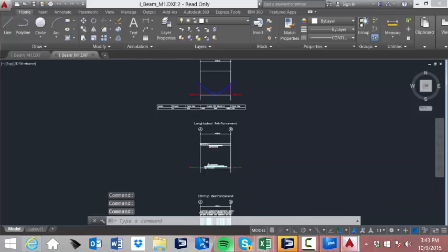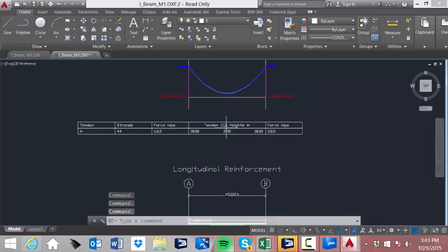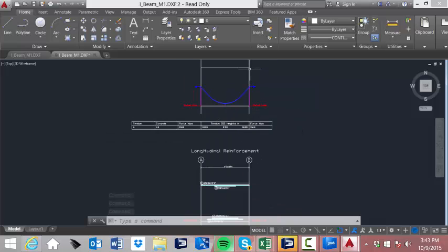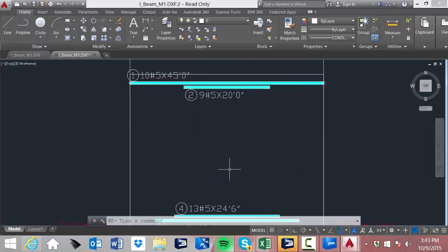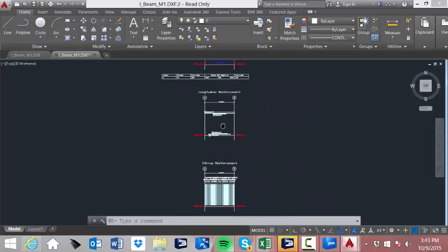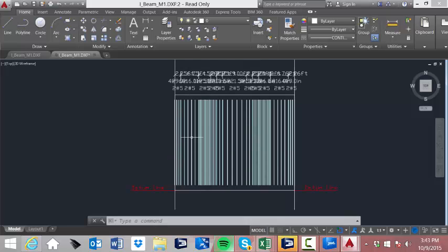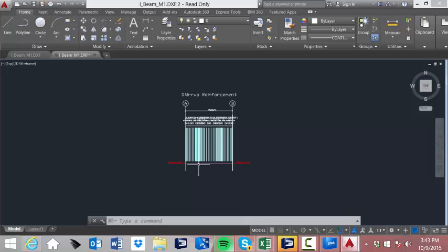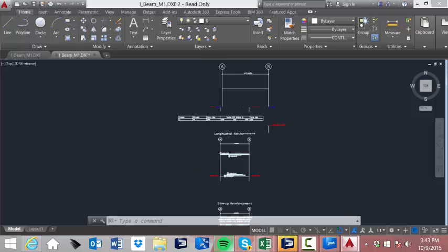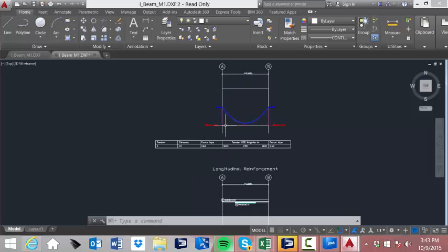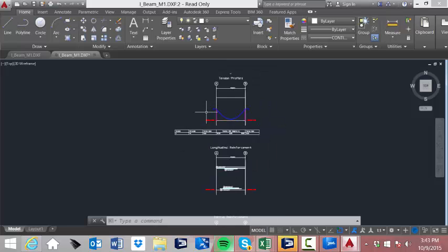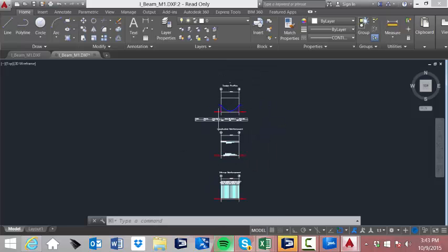So we have, again, a schematic of the beam. On the top, we show the post-tensioning information, and then we have longitudinal reinforcing information and shear stirrups shown here. And vertically, we've actually scaled this by a factor of 5. That's why the beam looks taller than it really is. But we can set that scale when we generate the DXF.